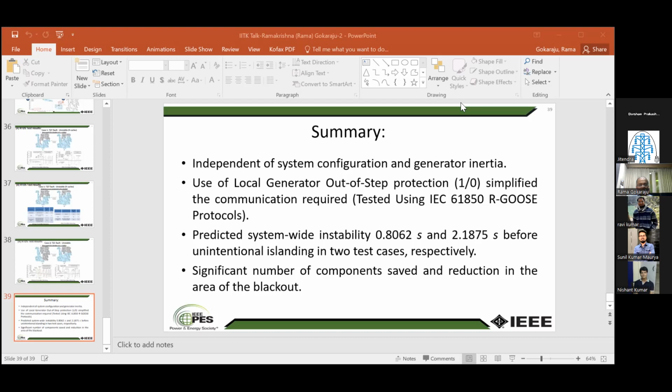They did not get a right of way, so building another line was not possible. So what they did is they put the simulations for this interconnection on an RTDS, and they run it in real time based on that operating scenario. They look at the line overload limits and, based on that, they do the power transfer on those lines. So they could avoid actually building a line.